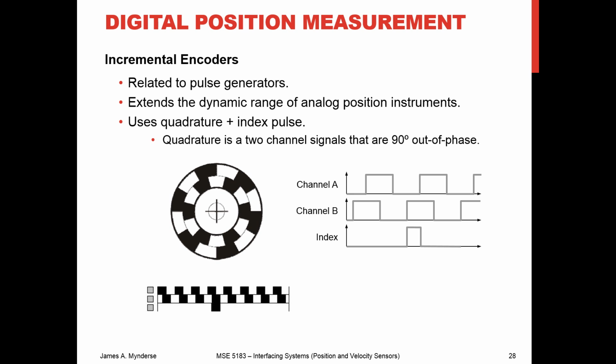So one type of position sensor is an incremental encoder. In this case, we've got a circular and a linear track. These two are using optical sensors, so we're using alternating transparent and opaque sections, and we've got the inner and the outer tracks, the two side-by-side tracks, and we might call these channels A and B. Then we've got an index on that linear one as well.